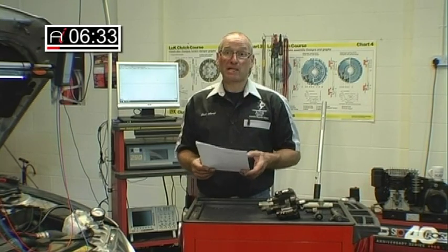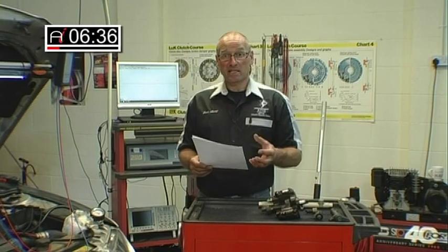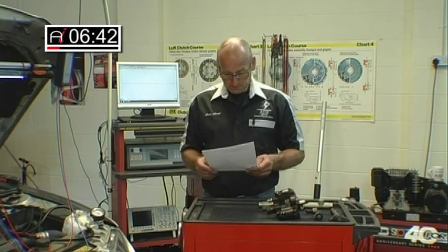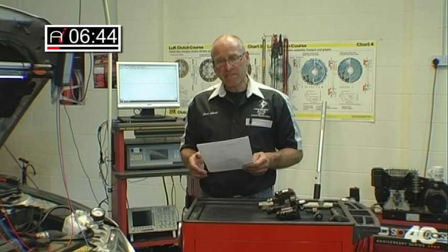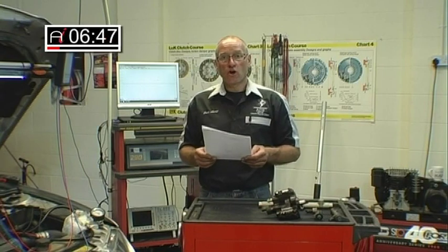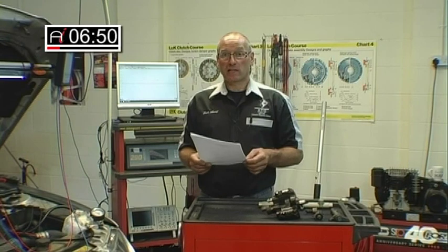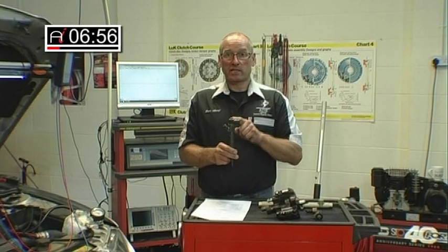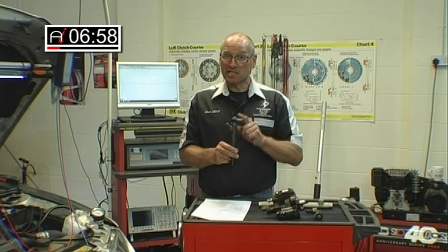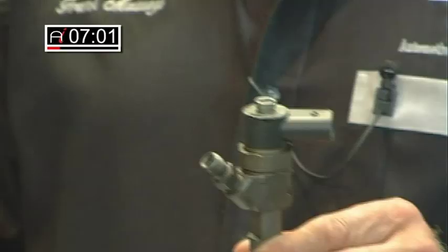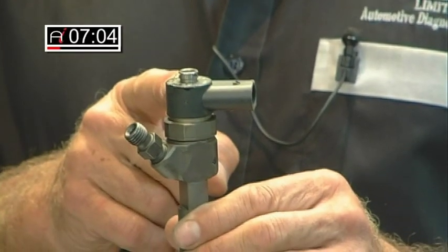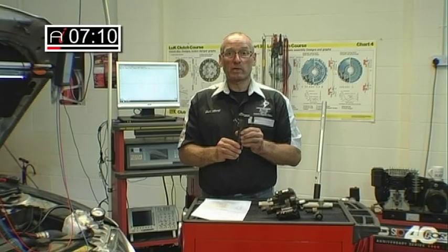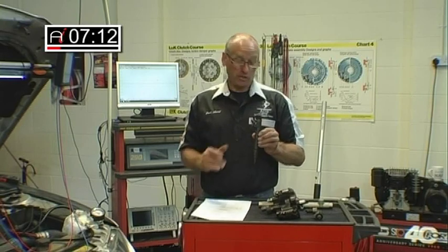But I don't know if that capacitor voltage is a man-made DTC, has somebody disconnected the injector and installed that particular fault. On this particular system, if that single capacitor fails or one injector were to fail, the vehicle will not run. It uses the closing event of the injector to partially charge the capacitor for the next injected event. So if an injector were to fail or the capacitor were to fail, this vehicle will not run. It will not start and or will cut out when in operation.